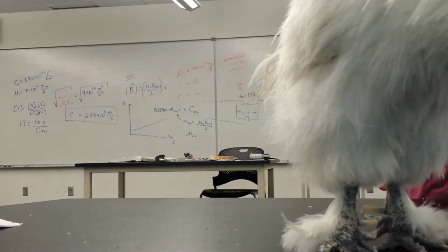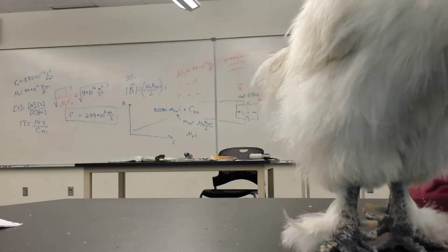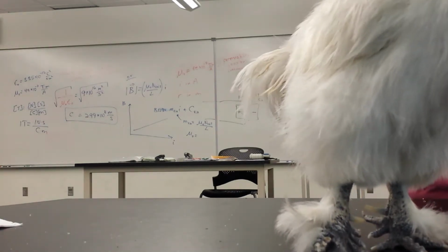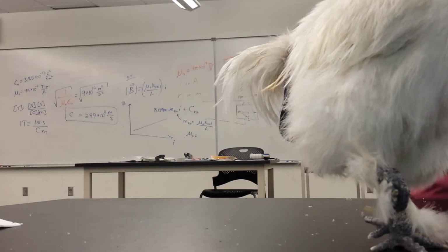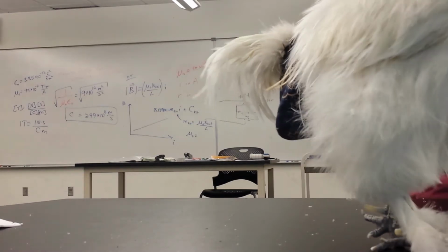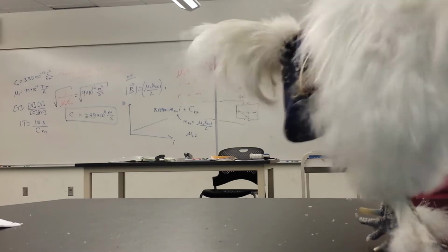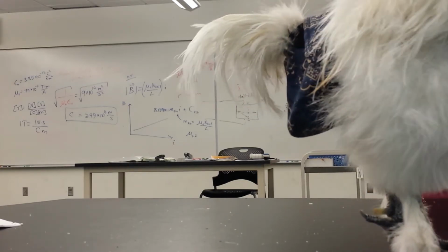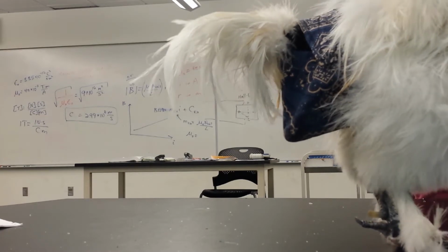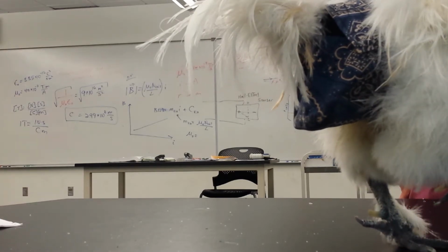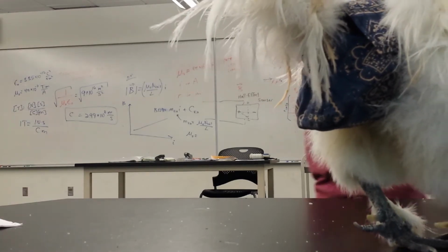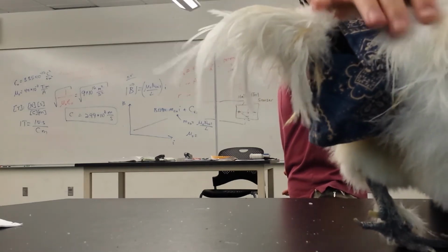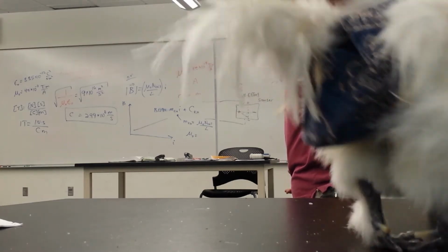Is this milliamps? No, the 10 amp. Okay. And by the way, you always measure current in series in a circuit. Always series, never parallel, because parallel basically shorts the circuit and draws big current away from where it would otherwise go. It lowers the voltage, everything goes, draws tons of current.